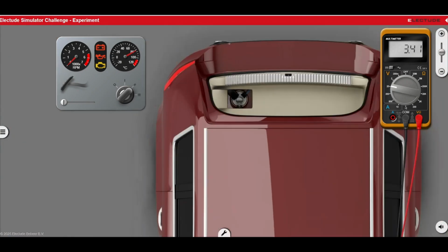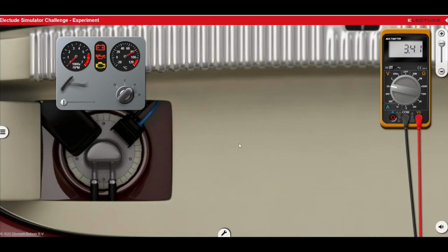The fuel pump is back here, in the back of the vehicle. When you turn the switch off, run again. You hear the pump running for a second. That is called the prime. It's priming for the engine to start without difficulty. It's trying to build up pressure before you even start the engine. Let me do that again.